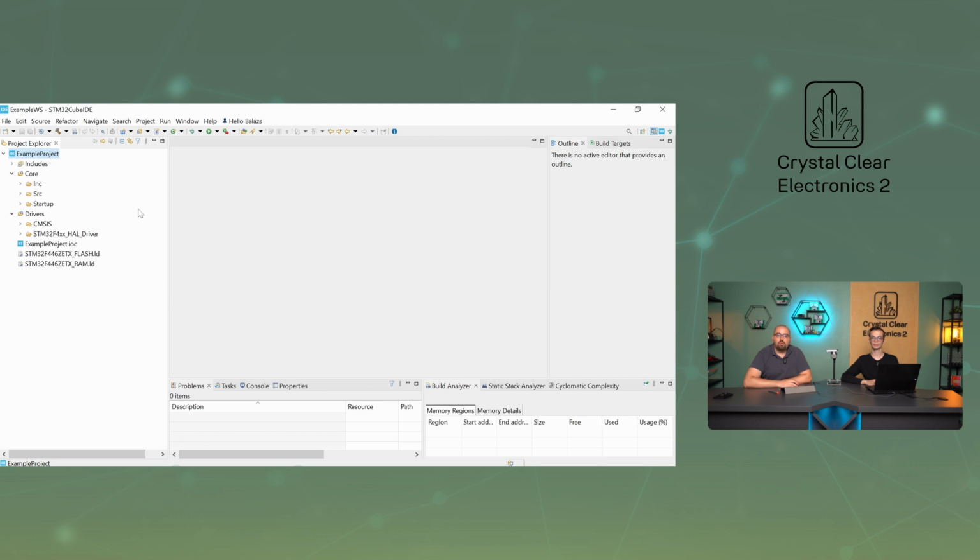During application development, the source files in the HAL library are very rarely changed and only needed for more complex applications. For almost all example codes, we will modify the files in the application category. We also do not modify the values stored in the registers. This is done by the HAL functions. Let's see what this theoretical structure looks like in practice. Here we can see the structure of a project using the HAL library, using the Project Explorer in STM32Cube IDE. Note that the files for the application are under the Core menu item, and under the Drivers tab, those belonging to the HAL library.